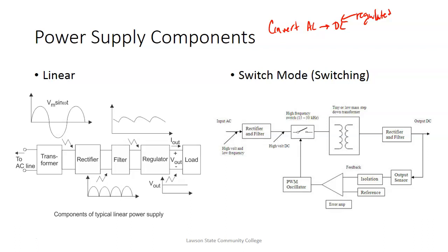Electronic devices like these transistors, they like a set voltage level. So the PLCs that we're using operate off 24 volts DC, but that's going to be within plus or minus maybe 5%, if better. That's saying between full load, whatever the load is, and minimum load, the output would only vary about 5%. So these are regulated power supplies.